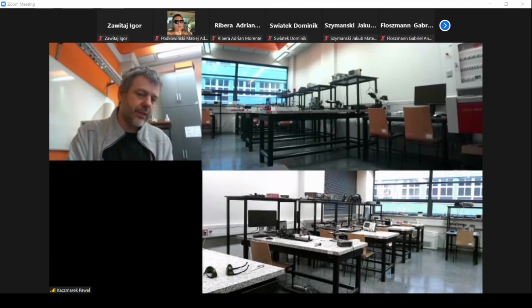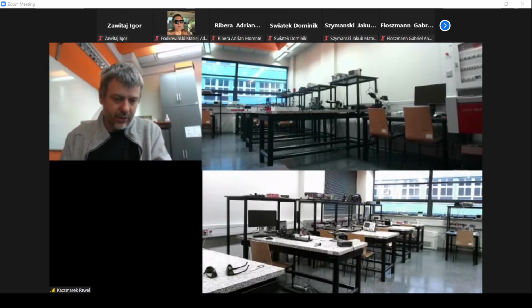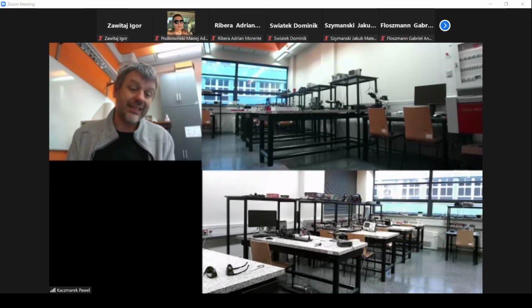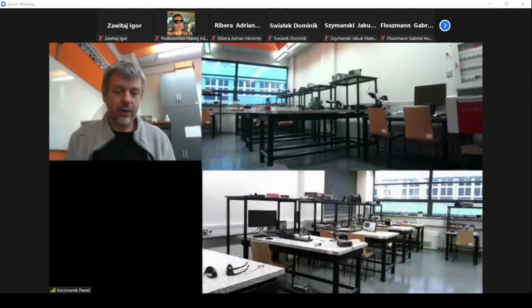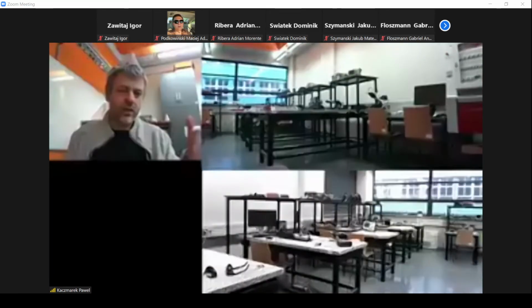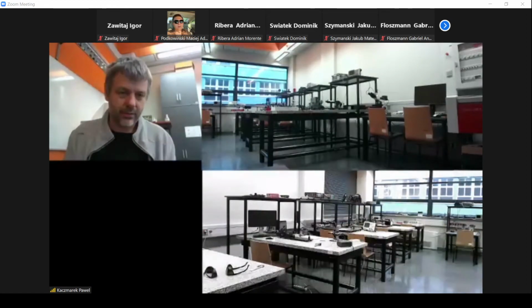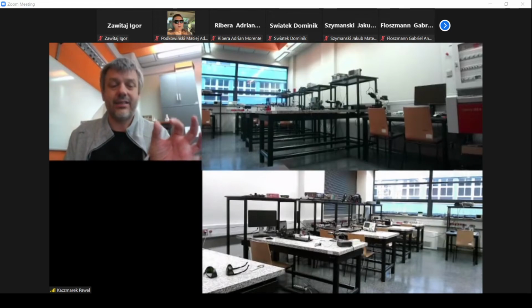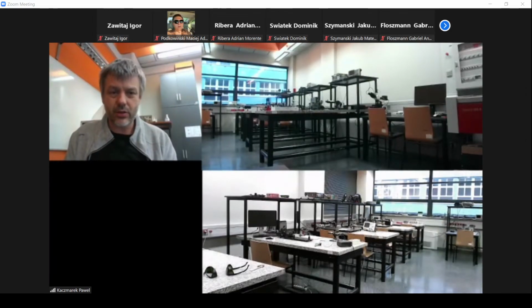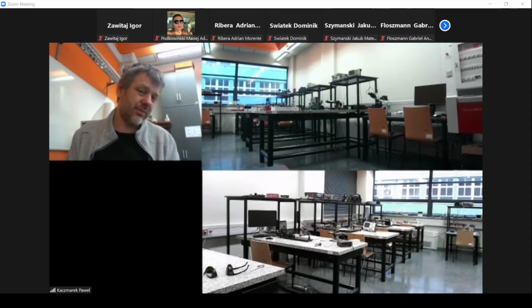If you want to connect fibers together, at first you need to cut them. If you cut the fiber, you have a lot of very small, tiny pieces of the fiber. They should be placed in a special container for waste fibers. But if somebody just leaves it on the table, it's in fact stealth, invisible to you. If you accidentally touch the table, it sticks to your hand, because it is very small and tiny. And you take your sandwich with this hand, for example, you can accidentally eat a very small part of a glass needle, in fact, because this is the fiber. If you eat it, it sticks somewhere in your stomach and it will stay there, I think, forever. It gives you a lot of unpleasant, let's say, phenomena.